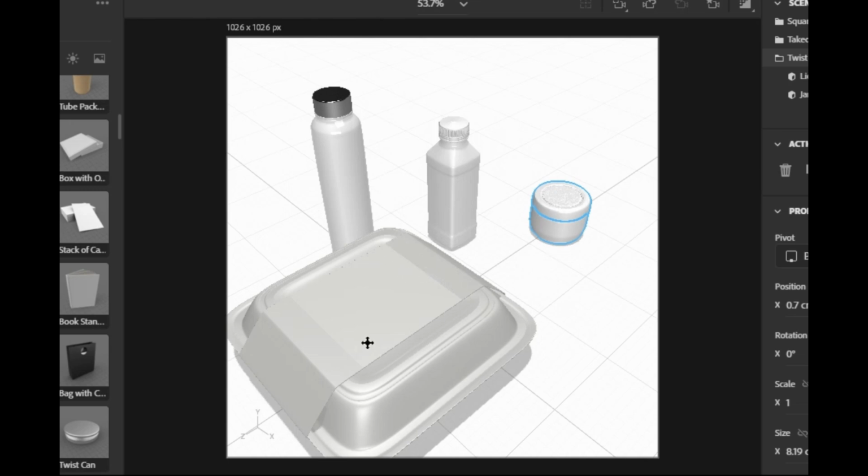So if we want to use selection tool, simply press V on keyboard and you can see the change in cursor, and that's it. You can see the change pointer and also object having the gizmo. With 3 arrows we can move the object. Using this small square on the axis we can scale the object, and using this circle we can rotate in the direction of x, y and z, and the center point is pivot. So by default the selection tool having a gizmo move, scale and rotation.